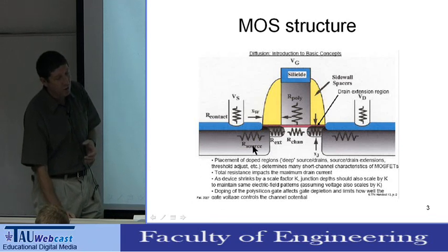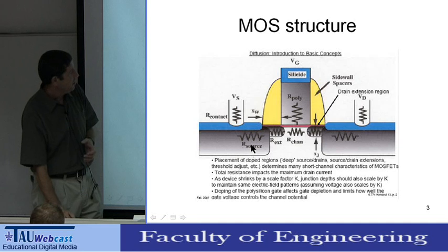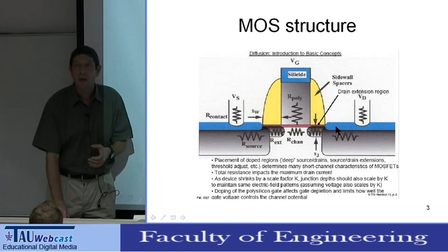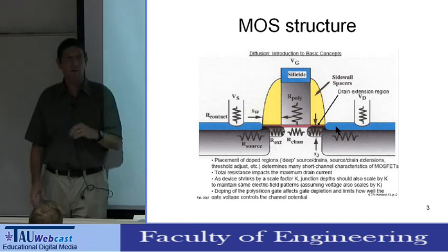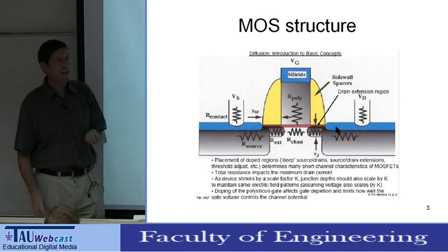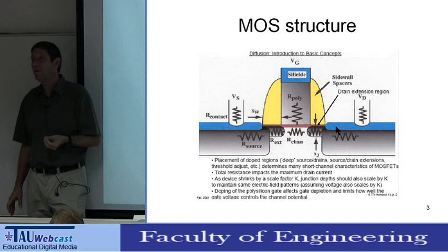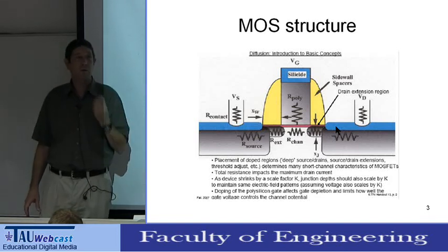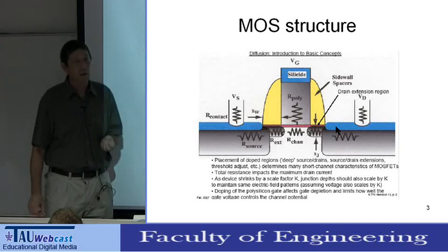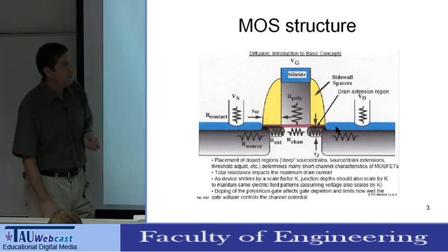You can see here a junction, and the blue layer on the side is the alloy, a combination of metal and silicon. It can be a nickel silicon compound, which is called nickel silicide, or titanium and silicon, typically titanium disilicide, TiSi2, or cobalt silicide, and so on.